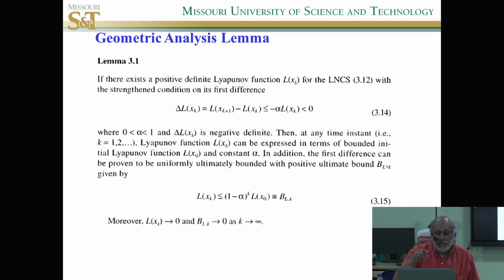So what does it mean by L dot less than or equal to minus alpha times L? So the system energy is decreasing. The Lyapunov function is nothing but your energy. So how many of you read about Lyapunov stability?